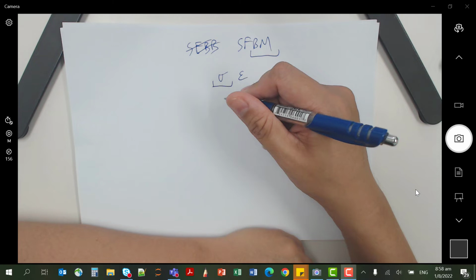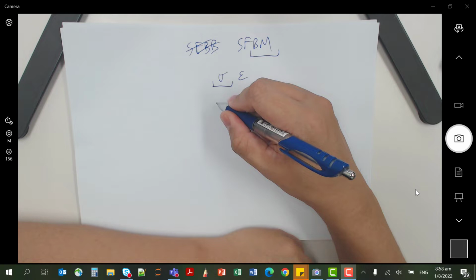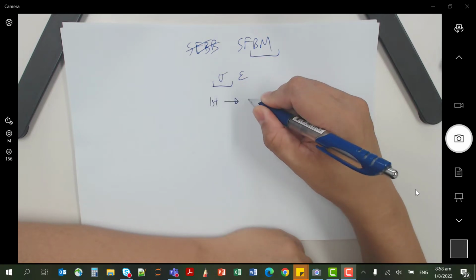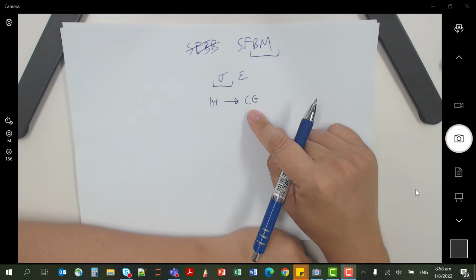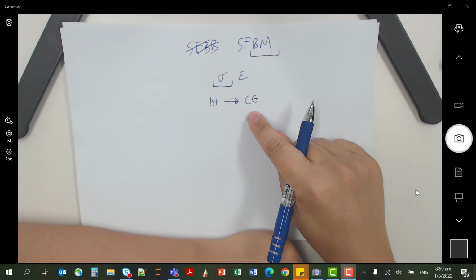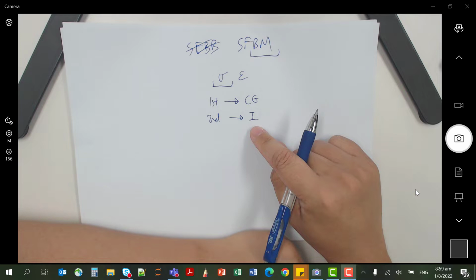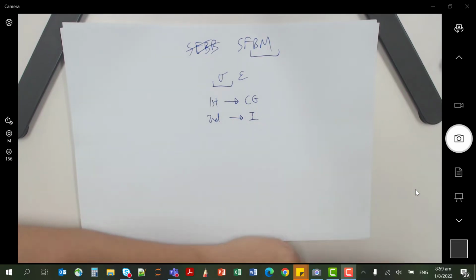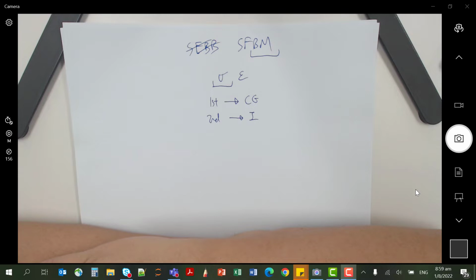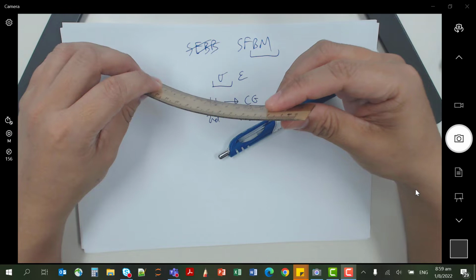The third one is the last topic, your first and second moment of area. The first moment of area is to find the center of gravity of a shape, usually the cross-section area of a beam. And then the second moment of area is to find I, which is the moment of inertia. Like I previously said, it is an indicator of how resistant your beam is to motion. For this case, how resistant is your beam to bending?